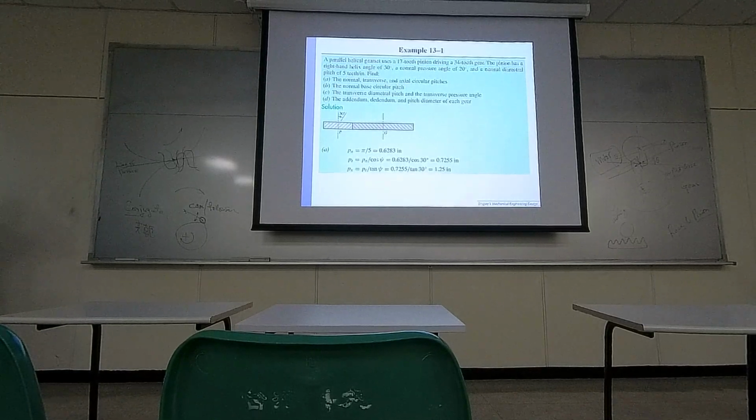So when you do that, you introduce a new angle, the so-called helical angle. You describe how the profile of the teeth changes its angle rotated about the axial axis, the central axis. So there is an angular difference. Okay?